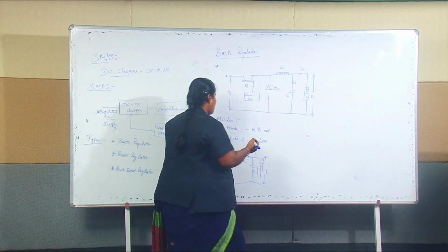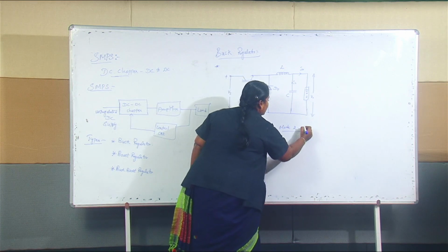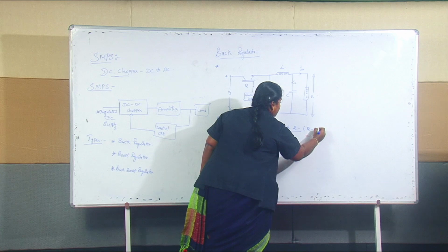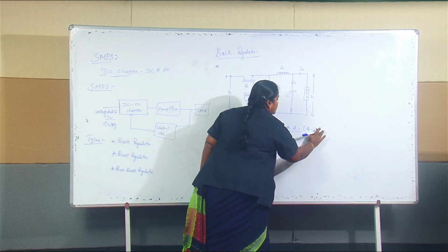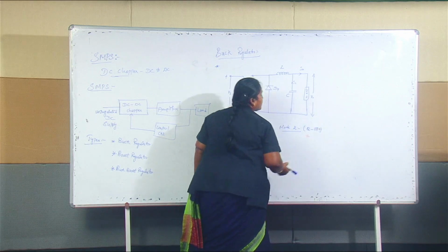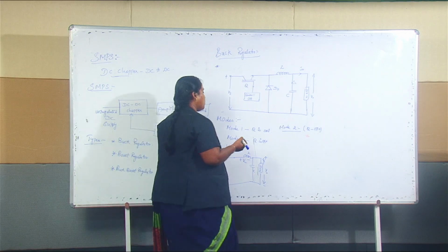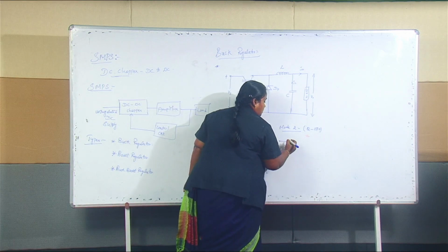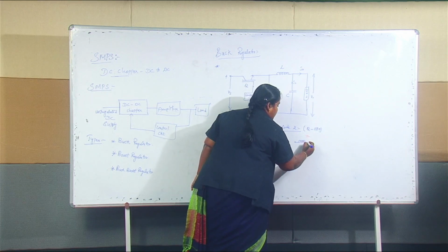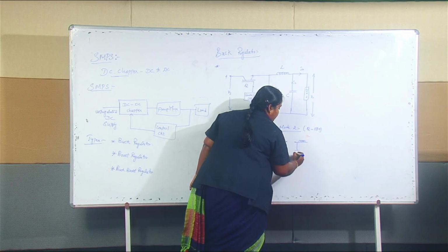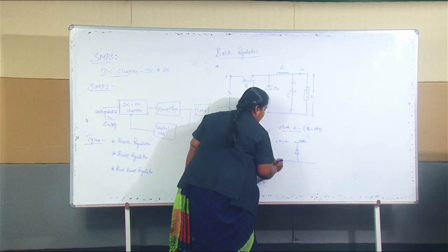And in the case of mode 2 operation, we have considered your transistor to be turned off. Off in the sense it is nothing but an open circuit across the switch. So the equivalent circuit across this transistor will be open circuited, and next we have an inductor, and along with that we have a diode across this. Now only this diode gets into play.